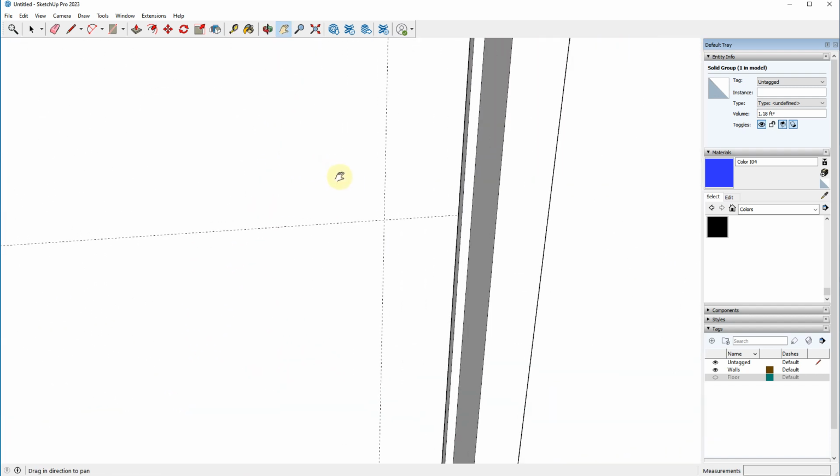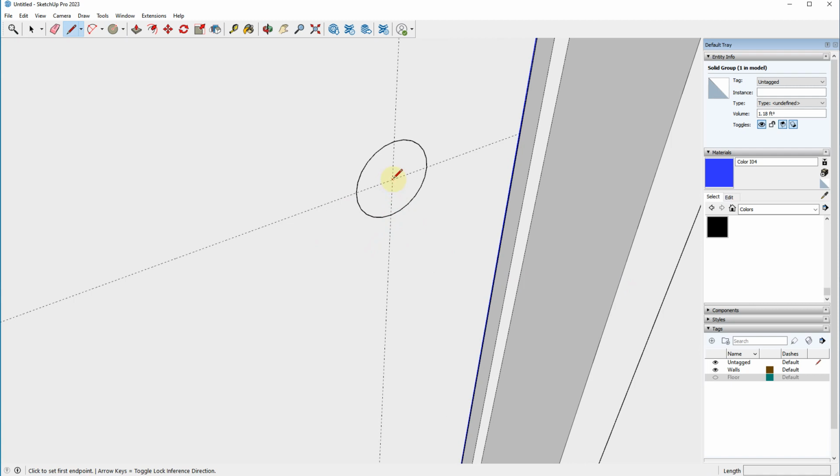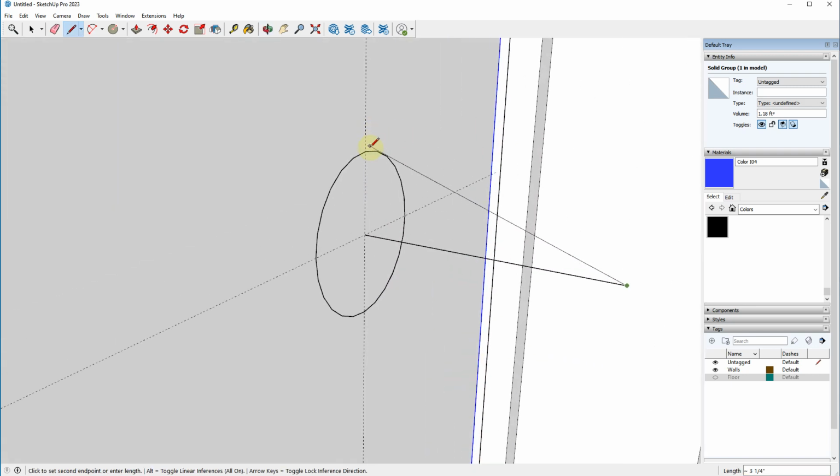And then, just like I showed you guys how I did that lamp the other day, what I'm going to do is draw a 1-inch radius circle right here. We'll do a line from the center here going straight out. 3 inches is good. And then I'm going to come right here and we'll create this profile. So I'm going to snap to the red axis, hold down shift, go to right there so that it lets me connect this. So now I just do a second click and it's good. We'll close this here as well.